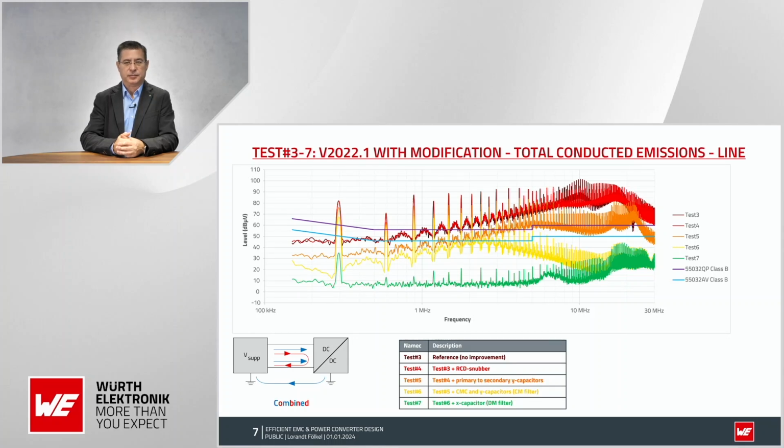I was not that happy, because even though the noise was much lower, I always expect from everybody that when I help in the designs, I expect to have at least 10 dB distance to the limits. I know many people say I'm crazy, but I like to have this 10 dB distance because, you know, you have a tolerance between components as well. You have tolerance from the manufacturing anyway. And I will always request, if you are 10 dB below the limit, you're always safe. You will never be punished under any circumstances.